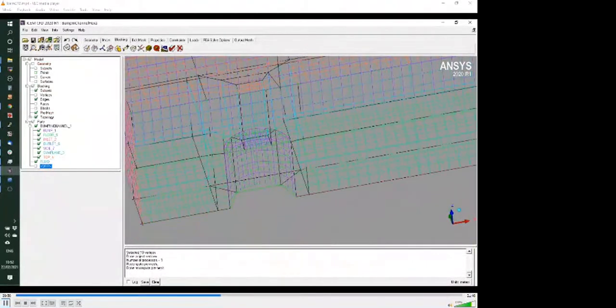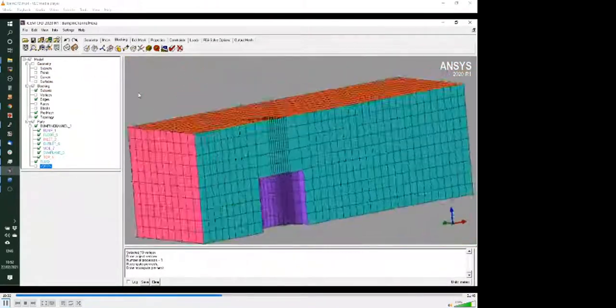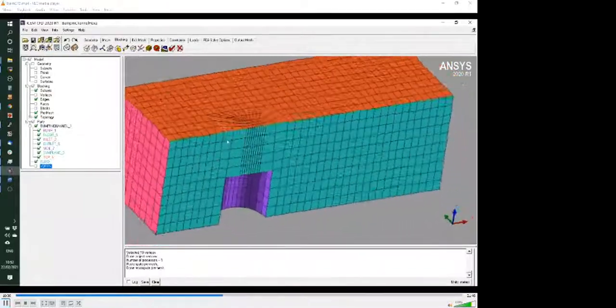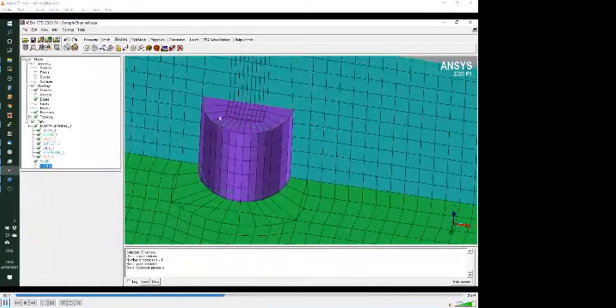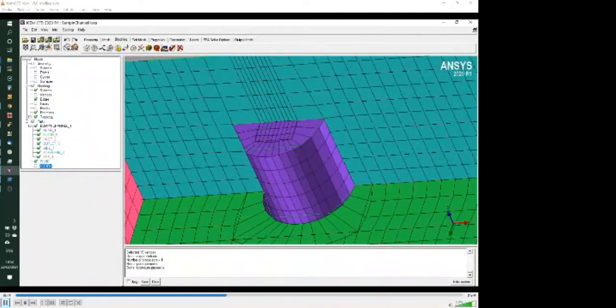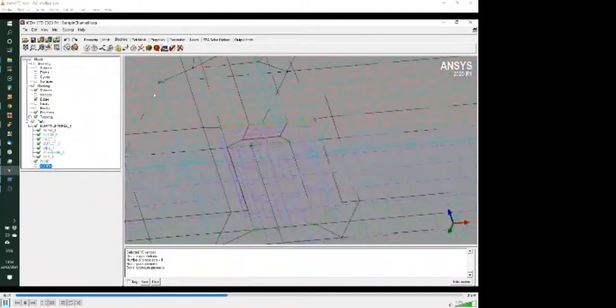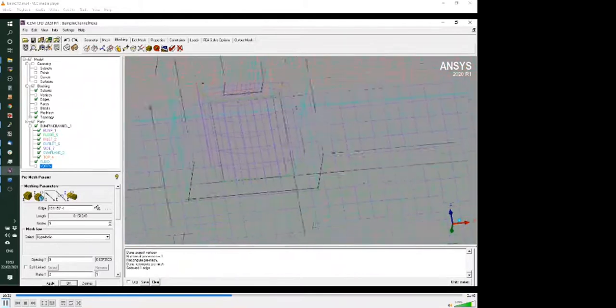Let's switch off the geometry and shade the surfaces. And we can immediately see that we've got something that looks a lot more like a mesh, but the spacing is rather horrible. Where we've split the mesh, it has not always given us enough mesh divisions, but that's very easy to fix. Let's just switch back to wireframe spacing. Let's say we put 5 mesh divisions along there. That should solve most of what we're dealing with.